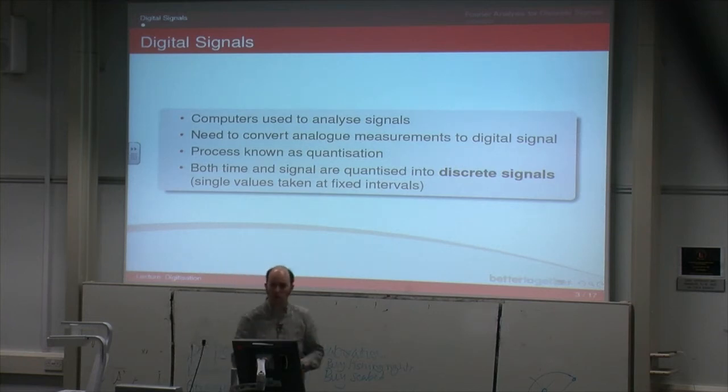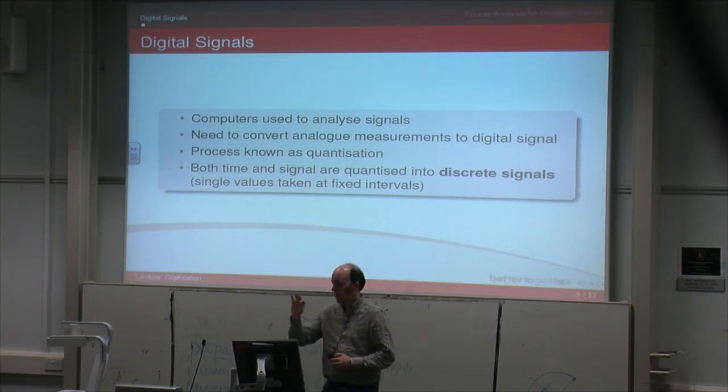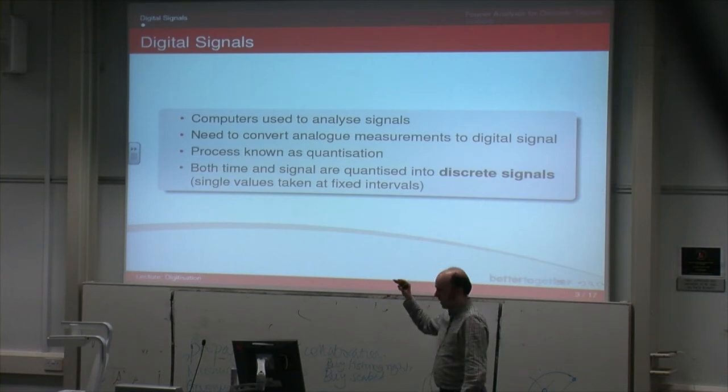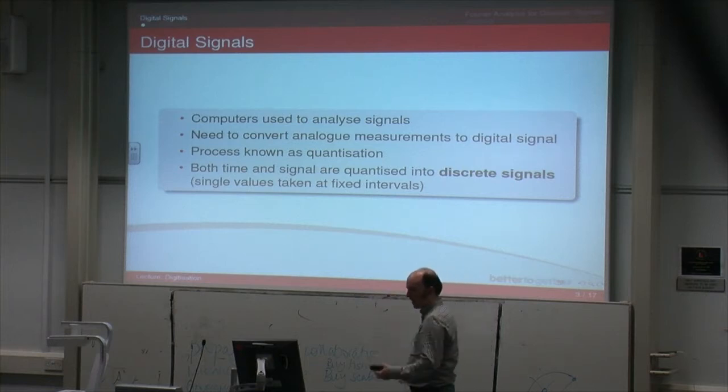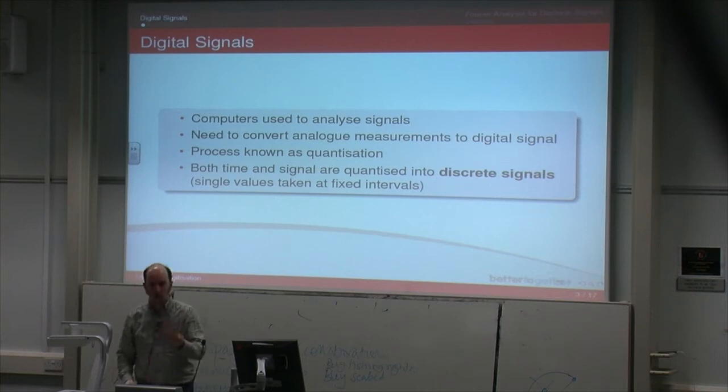So you have an analog signal, okay? Doesn't matter what it does, but you can follow that line no matter where along you've got it. But the thing is that with a digital signal, you've only got discrete positions that thing can be at, okay? And depending on how many bits your processor can deal with, gives you the resolution, or how closely your digital signal will represent the analog signal.